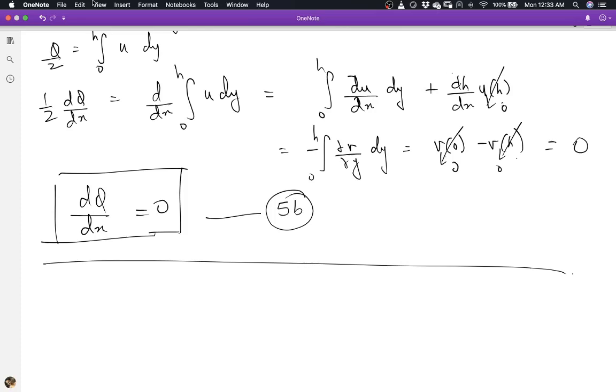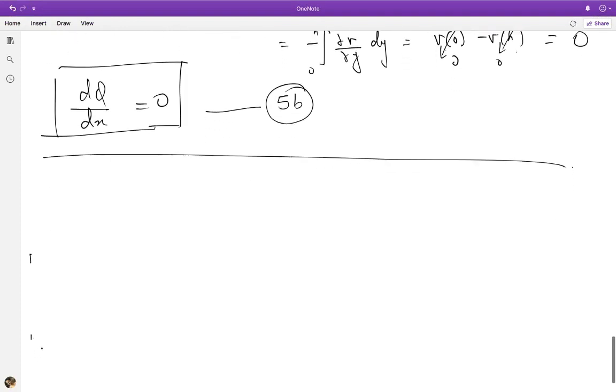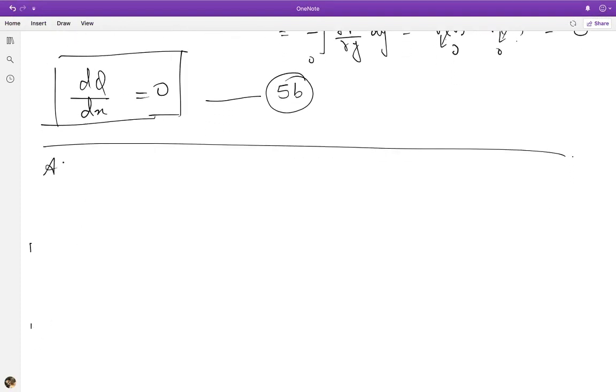So let us begin at the zeroth order. Now this problem, of course, is just that of flow between flat plates. The governing equations, as I said, stay the same. It's only the boundary conditions now which reduce to u0 and v0 equal to 0 at y equal to half for the top wall and the corresponding symmetry conditions.